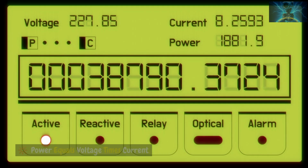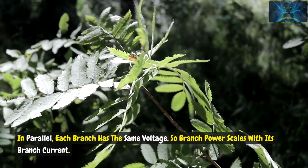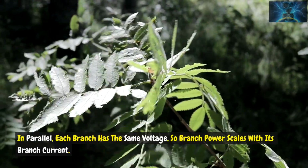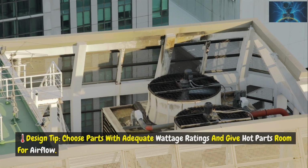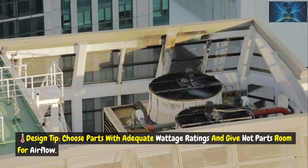Branch power and total power, why heat happens. Power equals voltage times current. In parallel, each branch has the same voltage, so branch power scales with its branch current. Total power is the sum of branch powers, which is why adding branches raises the total draw and the heat that must be managed. Design tip: choose parts with adequate wattage ratings and give hot parts room for airflow.